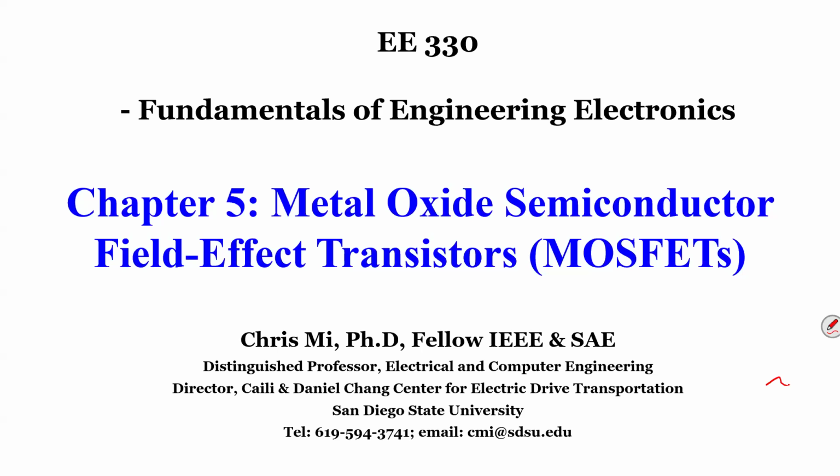Okay, let's get ahead. This class actually gets more difficult at this point. Look at op amps: the reason you guys do well is that many of you have done pretty well in 210, so that was kind of a review. The problems are not harder than in 210. And diodes, of course, are very simple. There are only 3 operation modes: ideal mode, constant voltage mode, or a SPICE mode.